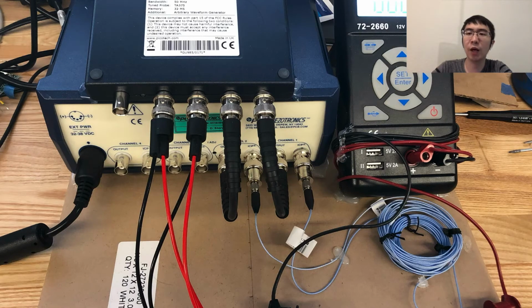Accelerometers were connected to an ICP signal conditioner, which is used to amplify and filter the raw signal. Because we are targeting time differences of arrival at the microsecond level, we use a PicoScope DAQ for sampling the signals from both accelerometers and microphones at 1 MHz.